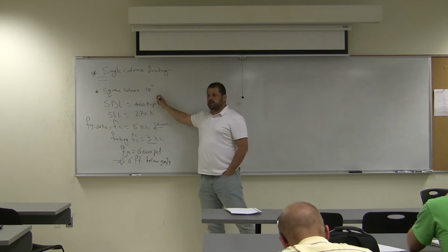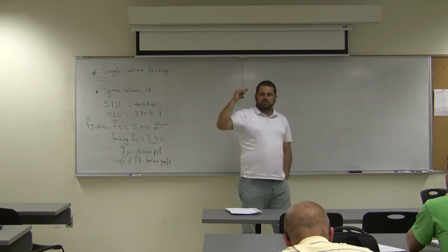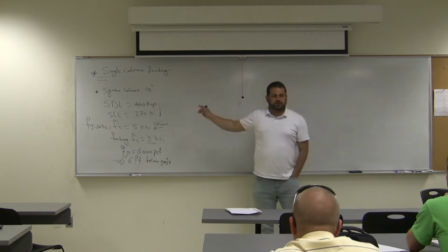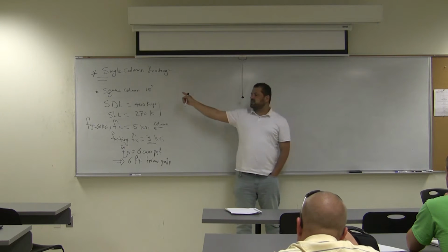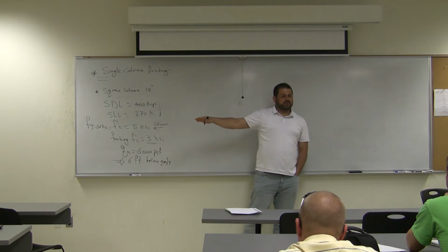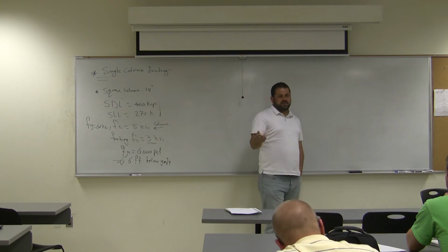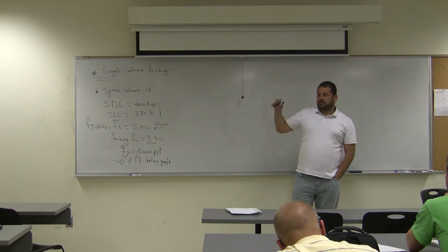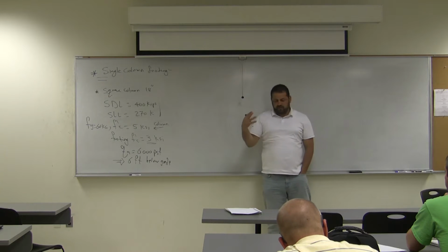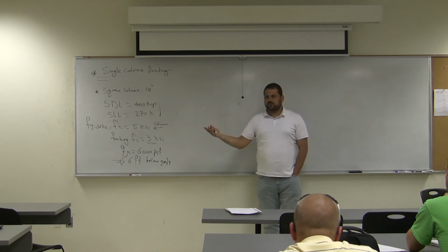So usually, guys, when you do any analysis in a building, always run your analysis from the service loads and the columns. When you give the column loads, try to give the service loads. Why? Because we use the service load on the column to calculate the area of the footing. Once we have that area, we magnify the load for strength design. Strength means shear strength and flexural strength design. Okay?